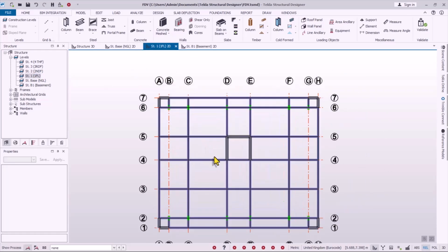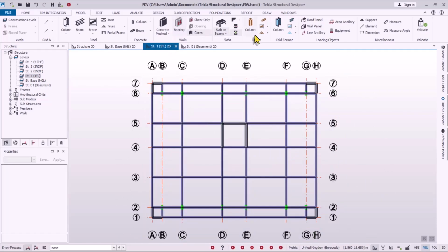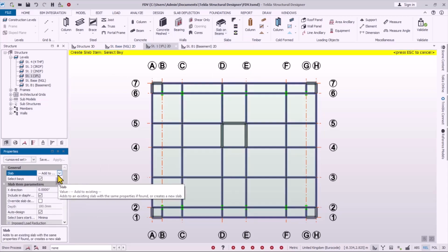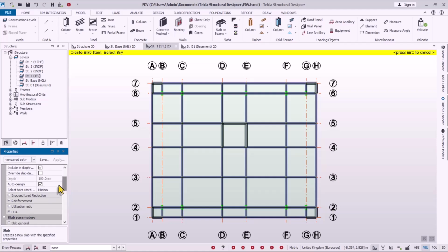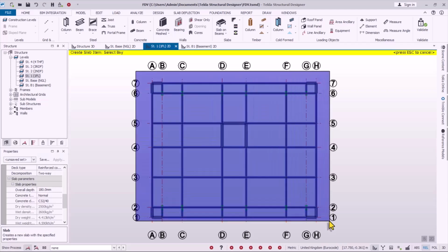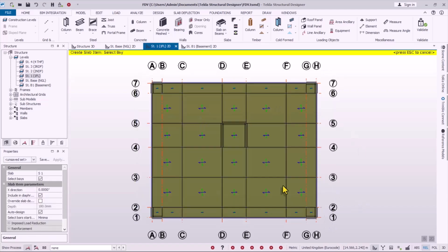All right, here we go. This is ST1. We click on the slab provision. All right, so we want to create an existing slab, next one. If you scroll down right here, you notice we have the depth keyed in before, so everything is good. Over here, it's a two-way slab, so you can do a window over the beams, release your hand to have a slab placed successfully, just like this.